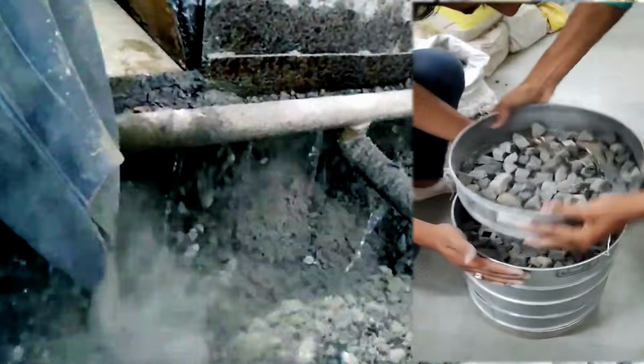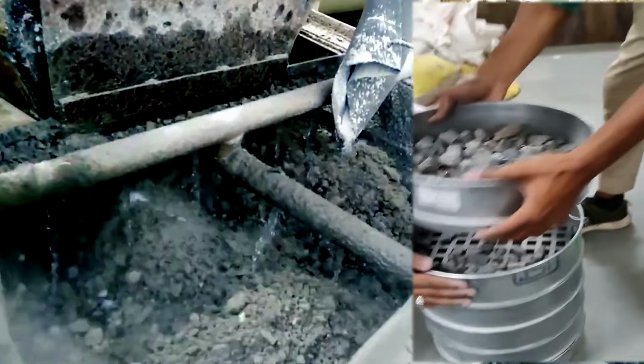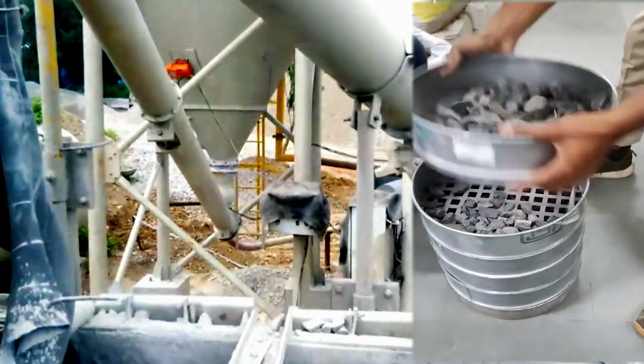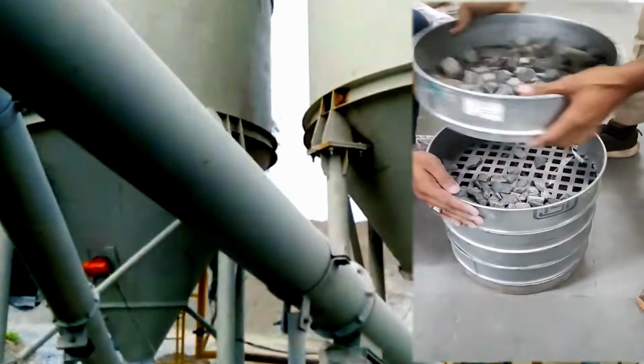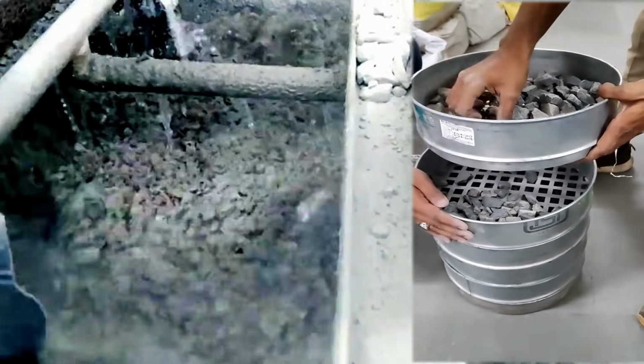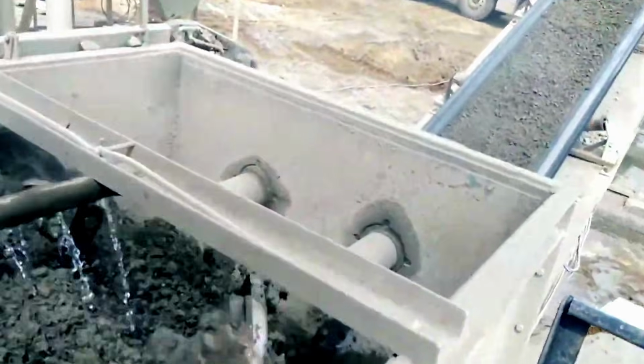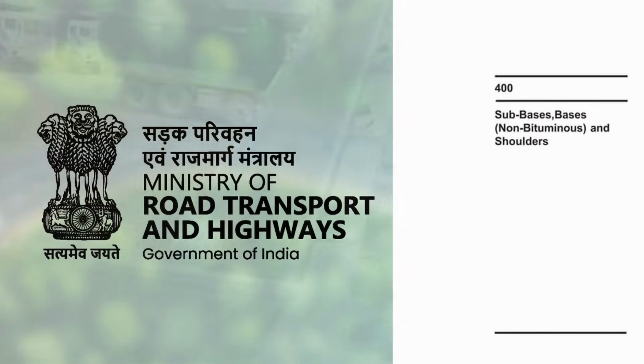The specification of materials for wet mix macadam shall include gravel of 0 to 6 millimeters crushed aggregates and stone aggregates of 6 to 50 millimeters. The proportion of this blended material shall conform to the grading requirements as per the relevant specifications. In India, MORTH Section 400, Table 13 is followed.